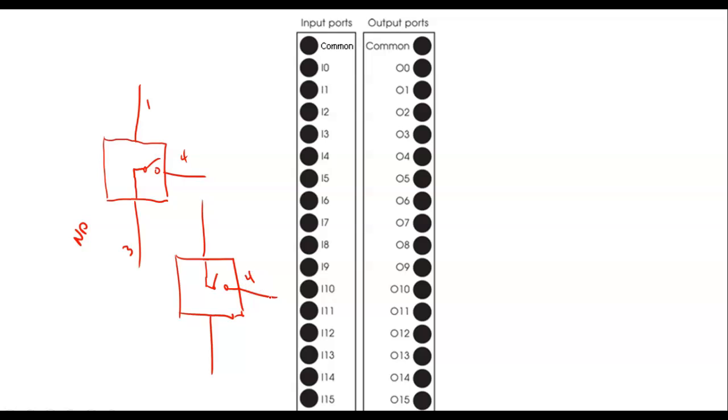So it's up to you guys when you have a sensor that's bad that you make sure you buy the right one. So an inductive sensor is an inductive sensor. If it mounts on your mount, then you don't have to get it from the same company because the wiring is the same. But you can't go out and buy what? So on ours, we need to make sure they're PNP sensors. Because what it's doing, it's electronically switching the plus out. And so what happens, if I came over and used this one, this guy is using minus as its common. This guy's using minus as its common. We have no current flow, so it appears that the sensor's bad.